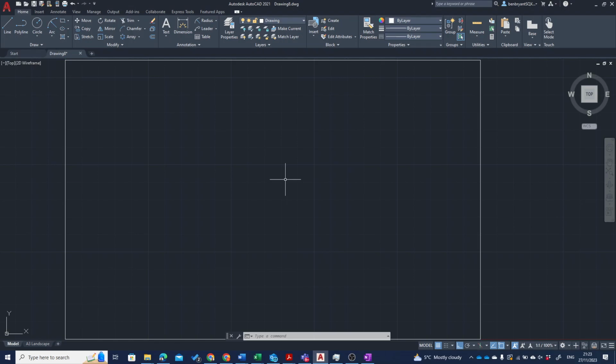So on my set location, I'm going to do the line first, so L for line. And my first coordinate is going to be my 175 by 100. I've already pre-locked my orthographic, which is down here, so it only snaps in 90-degree segments, or F8 if you have a function keyboard. So I'm going to just push that one up on my mouse, type in 25. That'd be my first locked in element here.